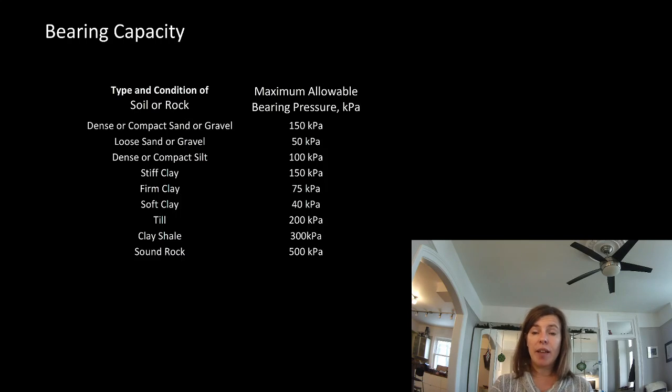I had a project that was going out last year in a rush. Actually, I had 2 projects going out in a massive rush. And both of them I said, the biggest risk here is that we don't have a soils report yet. We should focus on getting that ASAP. Everyone was so busy and the owners weren't as experienced as maybe we would have hoped. And the soils report didn't come to us until late in the project.